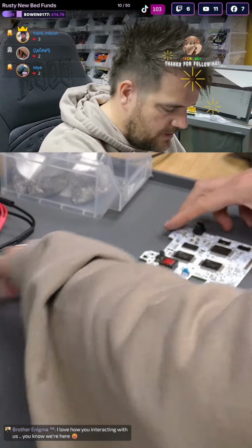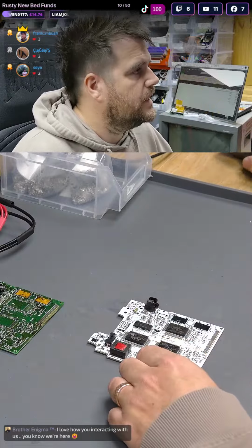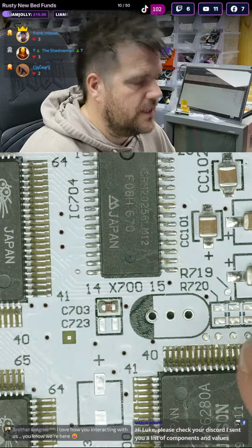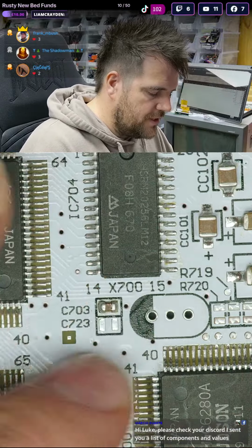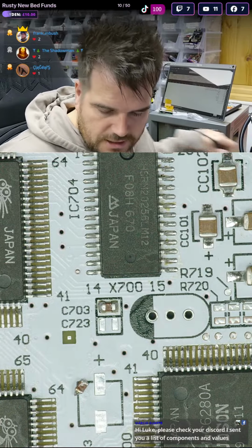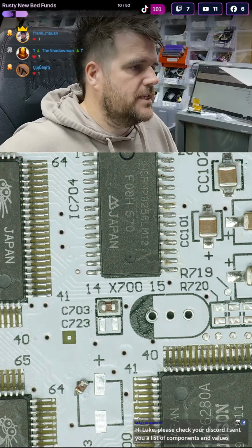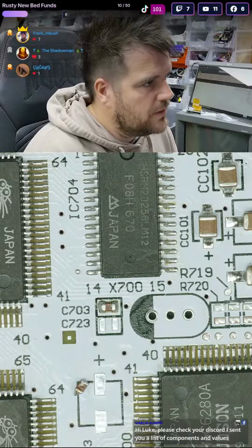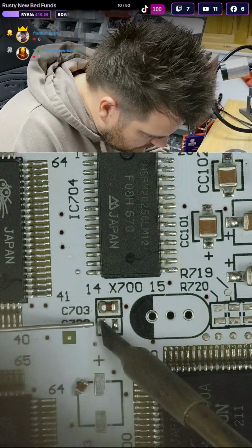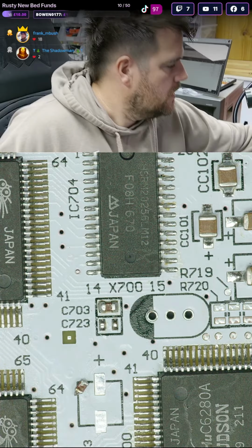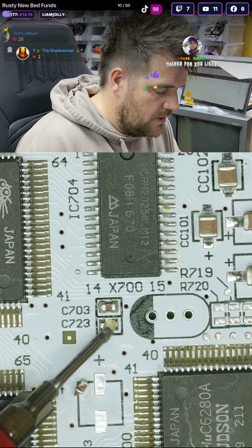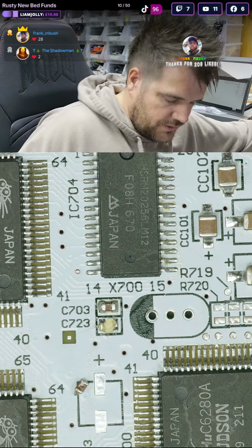They're one of the things where you really need that accuracy, because if this is related to this crystal here, it'll be related to the oscillation and the stability. It's a crystal load capacitor, at a guess. So it loads down this crystal and makes it oscillate correctly, so it's a crucial value. The fact it's right by the crystal, I'm almost guaranteed it's going to be that, and there's not many more uses on this board for such a low value capacitor other than a very high speed crystal circuit.